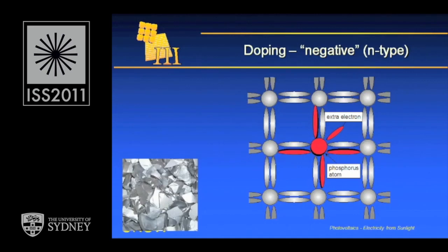It's conduction associated with electrons, and fortuitously, it's known as negatively doped material, or n-type material is the common terminology. So I think most people have forgotten that the n refers to negative. It's become such a common terminology, n-type. So adding certain impurities, you can get this negative type property.